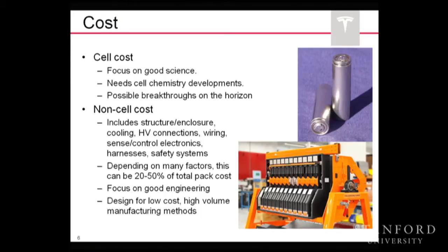Inside a Roadster battery pack or a Tesla battery pack, there's what they call a battery management system board, one board that takes responsibility for the whole pack. And then there's another board for every one of these modules, and it has all the little temperature and voltage sensing lines going out. And actually that architecture is not unique to Tesla. Most everybody who's building these days, it's great. You can see lots of people who cut open battery packs and look at what's inside and post videos on YouTube. And so you can go look and see how everybody else has solved this problem, and they're all solving it in the same ways. They have the BMS board to take care of the whole thing, and then these little BMBs that monitor individual modules. People use different approaches for cooling.